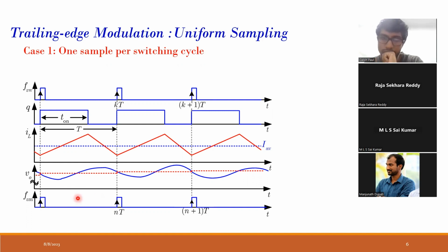Okay, so over here, we have not included that delay. In this one, I have not shown that delay, and you're correct. When we run in the microcontroller, we give a command at this time to take the sample of the signal. It will take the sample, and then after some duration it will finish converting, and the ADC will generate a signal saying, yes, I finished converting. And then the digital value is ready for us to read and to run in our algorithm. But in that time, there will be some sort of delay.